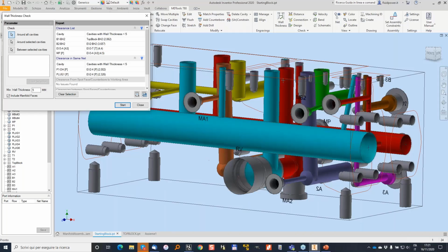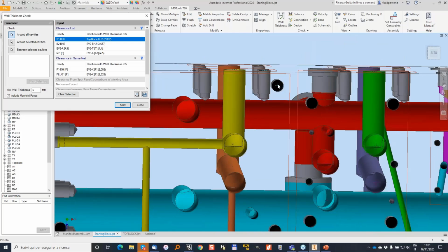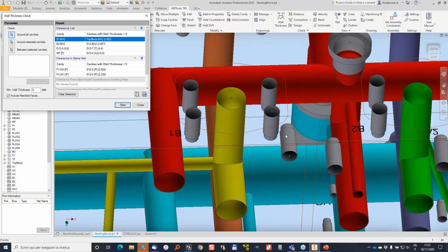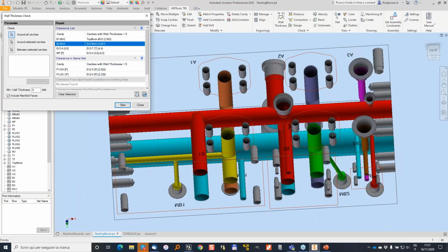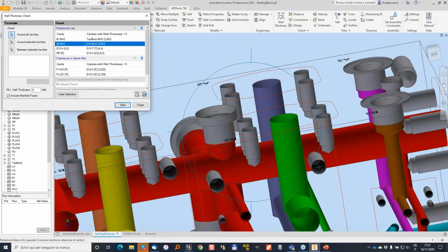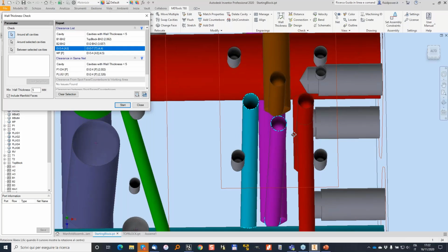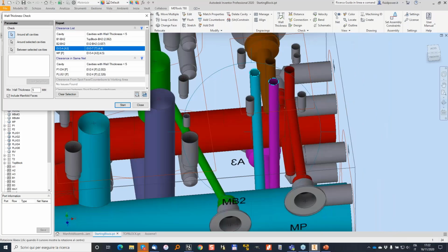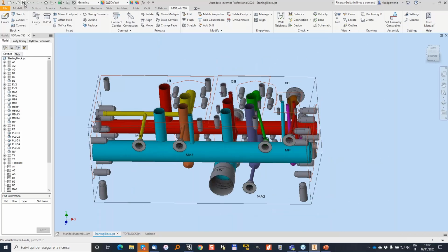And here we can go through, maybe here we see that we have not enough space between the bolt holes, but that should not be a big deal on the block. I don't fear anything here. And the same here, we have not a lot of distance between the bolt holes. And here we have just 4.4 millimeters between the blue and the pink drills, but that's okay. So we can go through each issues and fix if needed. But the block to me looks good, so let me save it.